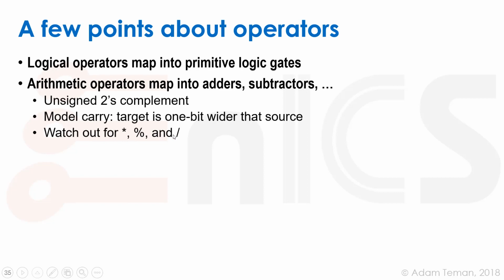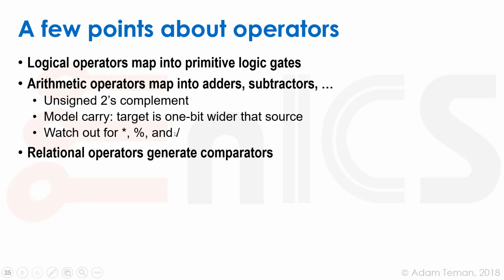And if you write modulo or divide, that's going to be a bigger problem, because modulo and divide are really non-trivial types of implementations. Okay, relational operators: bigger than, smaller than, etc. They make comparators. Comparators, again, these are a type of adder or subtractor, and so they're going to be big.